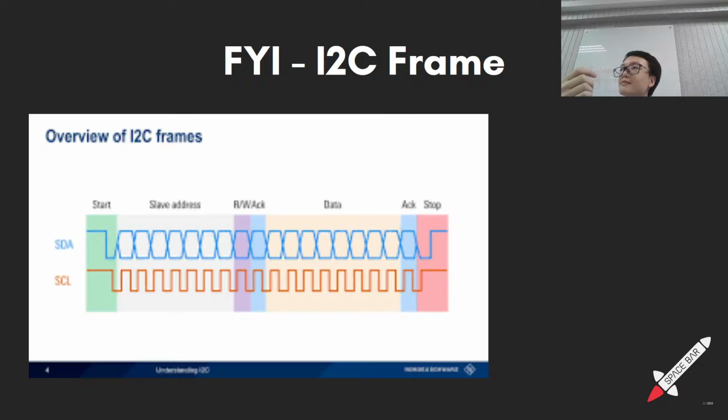Yeah, this is also for your information. For I2C lines, I forgot, there's something missing in this diagram. You actually have to put a pull-up resistor. Why? So you have to put like 2 resistors here, and they are connected to VDD 3.3 volts. Why do you have to do this?